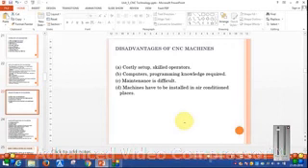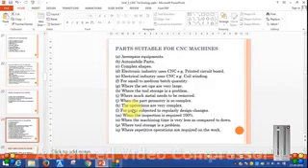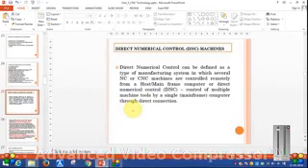But one main disadvantage of the CNC machines is that they have very costly setups and we require skilled operators. Then programming is also required, so information about G codes and M codes is also necessary. Maintenance is difficult. Machines have to be installed in air conditioned places. Then these are some parts suitable for the CNC machines.